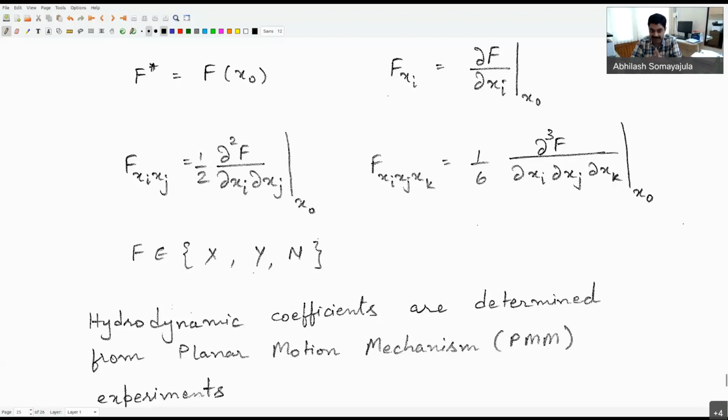So if I really don't have the experimental data for that ship, I may be able to choose the drag coefficient roughly from a different experiment which might have been performed, or somebody else has studied it in CFD. I can get a drag coefficient and I can use it in that sense.